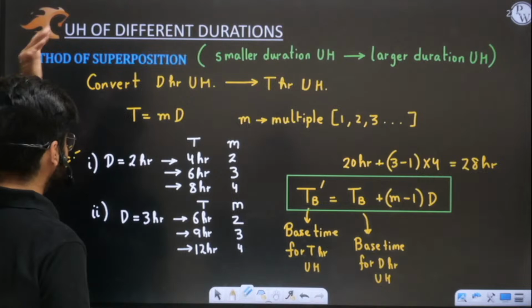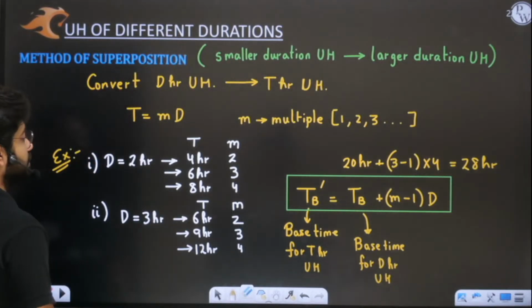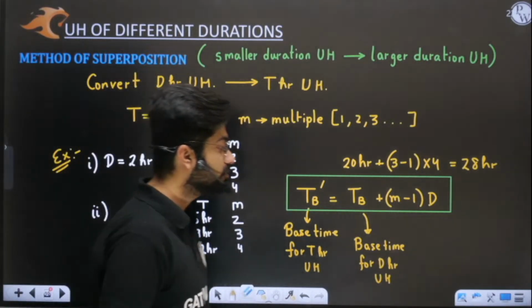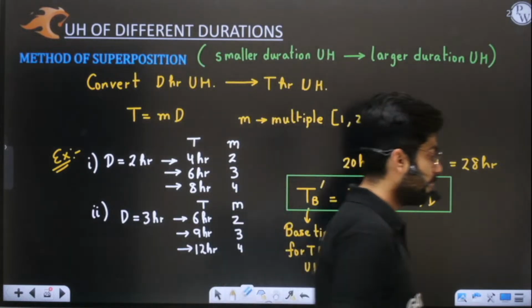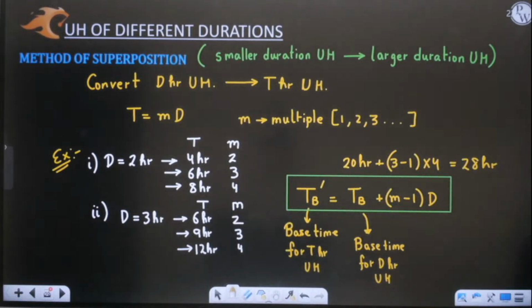But we have discussed only the method of superposition, and today we are going to discuss the S curve also. Yes or no? I also gave you an example in which I converted a 4 hour unit hydrograph into a 12 hour unit hydrograph. Do you remember it?